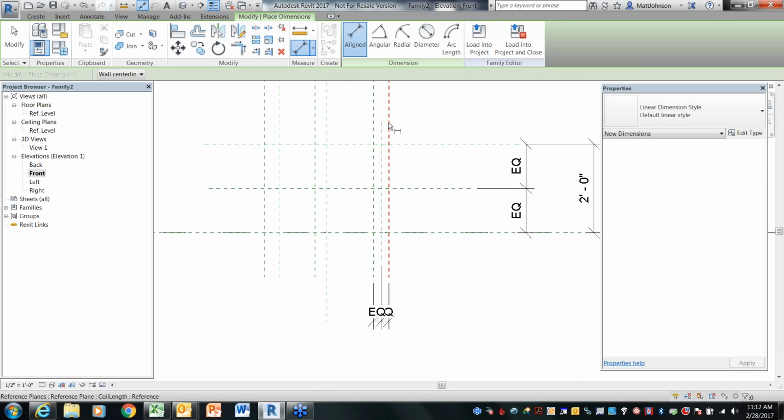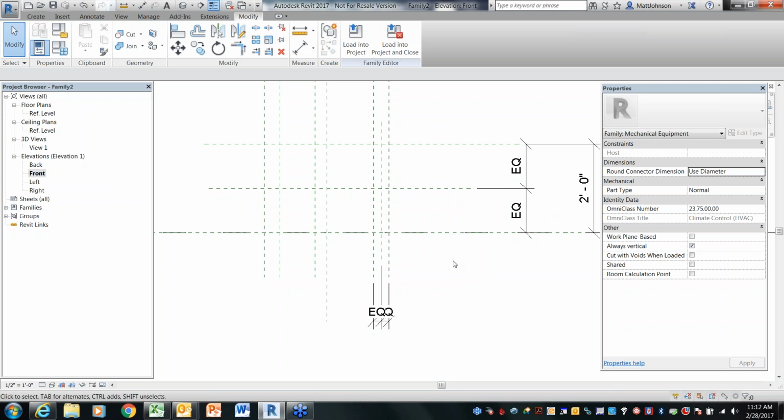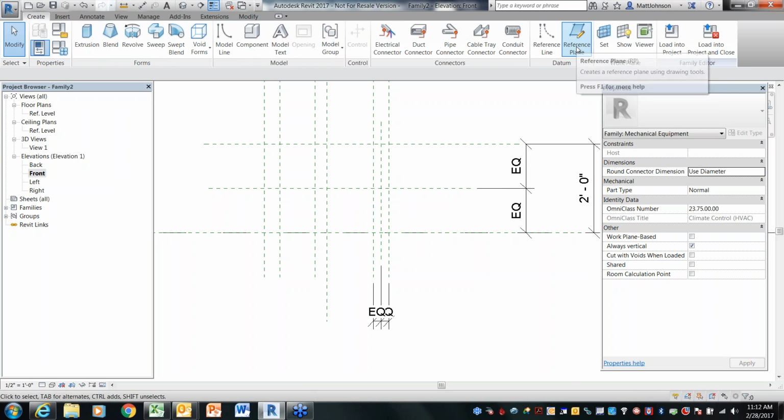And we've gone to the top, so we've already specified this one as the length. So as the coil length extends, this center line that we've created, do we name that one? This needs to be box center line. This one is going to be our pipe center line. Just want to make sure we name all these. Okay, and then we want to specify in the horizontal direction our height of where our pipes are going to be.